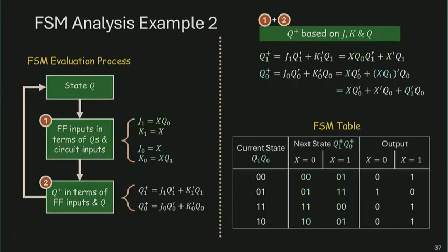Right, so here's what's actually happening when you put the combinational logic and the characteristic equation together. We substitute all of these JK variables with the corresponding combinational function as shown on the top. Things are color-coded, so you can quite easily see that these are the combinational functions getting into the inputs of the flip-flops.